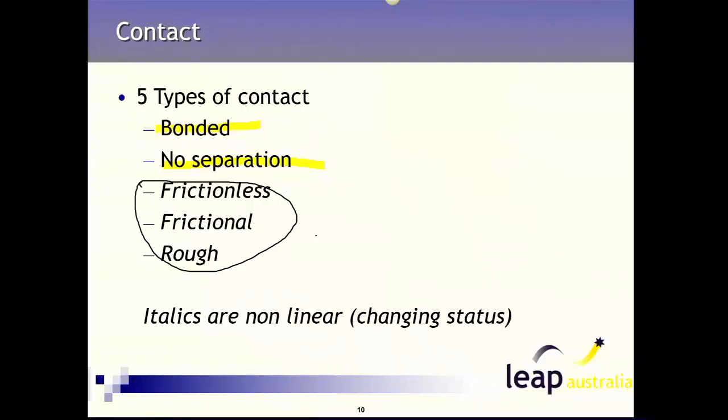When I say status, I mean the amount of area in contact, so you could go from parts being in contact to being separated, losing contact. That means that your load path will no longer be through that contact. So contact is probably one of the more challenging non-linearities to deal with, but there are parameters you can change within a contact that help achieve convergence.